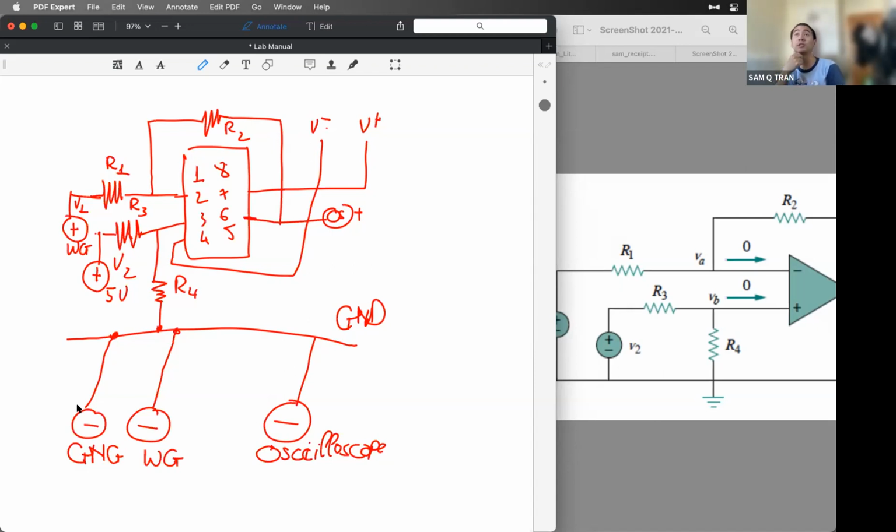But the idea of the EKG is that it's completely the same thing. For whatever sensor you have, the sensor value will vary from 0 to a maximum at either 3.3 volt or 5 volt, and anywhere in between. For example, you have 1 volt, so that means there's some EKG value associated with 1 volt, and there's another value for, for example, 1.2. It also depends on the resolution of the sensor and how sensitive it is. So the idea is you read the voltage of the sensor and use the info sheet to translate those voltage values into the actual reading.